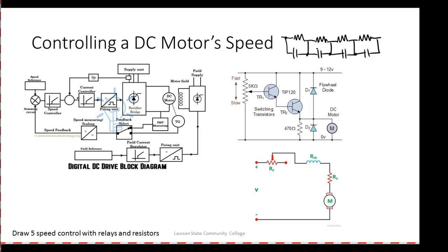And what would happen is that if all of them were closed, you got maximum speed, right? Because we bypassed all the resistors, and I would drop one in, add another resistor, and the motor would slow down. The problem is, though, resistors do work. So what you were doing is you're wasting a lot of energy in what? Heat. These resistors, guys, had fins on them. They were inside a big old cage, so you couldn't touch them because they really got hot.